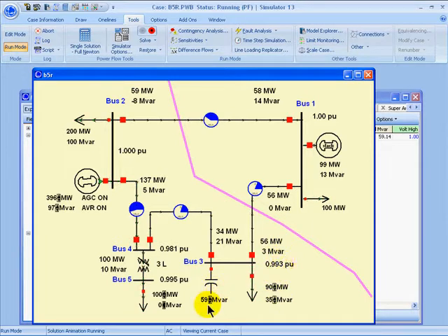So at a reactive power load of 35 megavars and 90 megawatts of real power load, the switch shunt then drops one of the blocks, and it's still within range. It's between 0.99 and 1, but it doesn't need as many megavars in the switch shunt. So if I continue to decrease that, I can see the voltage starts to come back up a little bit, and if it gets too high, then the capacitor will back off 1 more block.